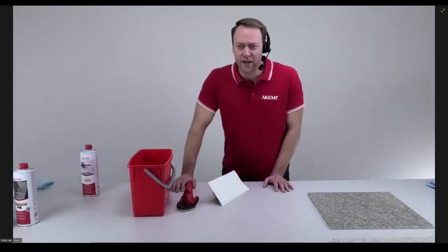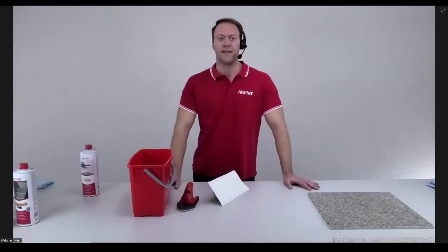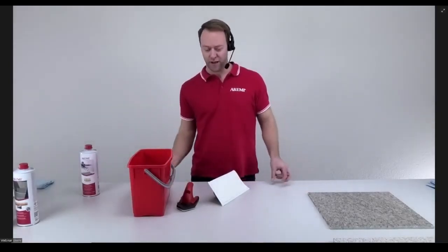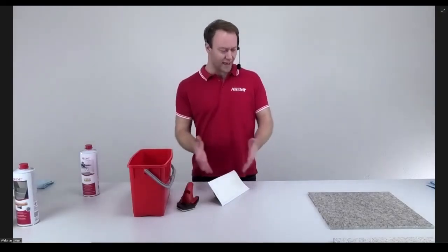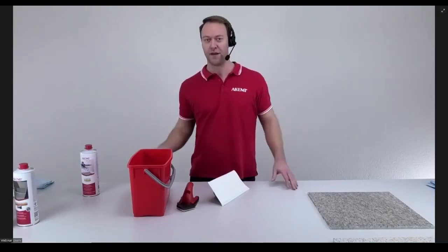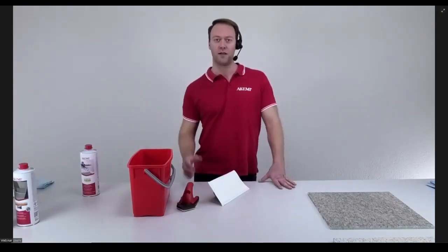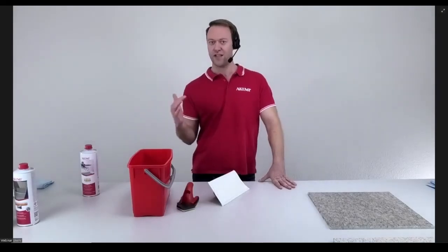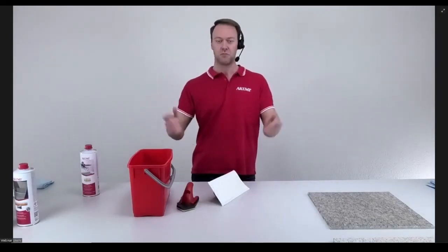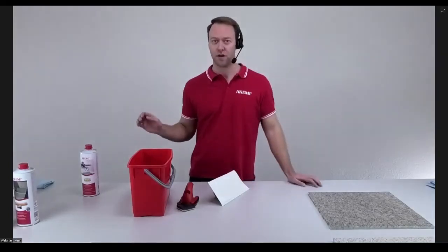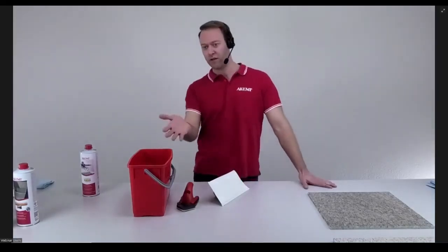Because limestone and marble is a soft material. The impregnation or the sealer would last many years actually everywhere. But the problem is with a marble or a limestone, when you have a polished finish, you can check that very easily. You take a polished marble, put it outside, and you just leave it for 6 months. And after 6 months, you check, the gloss is gone from the stone. Yeah, it's dull.